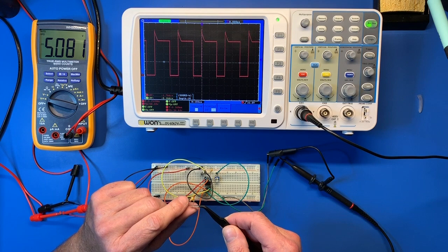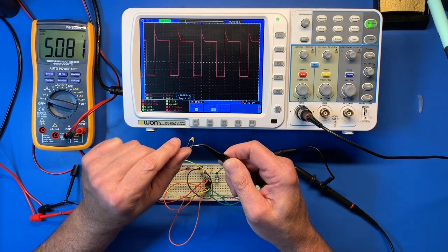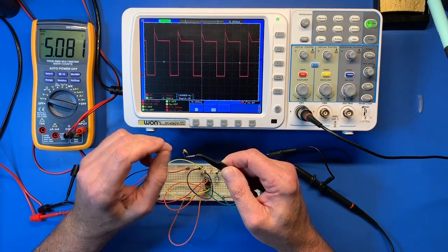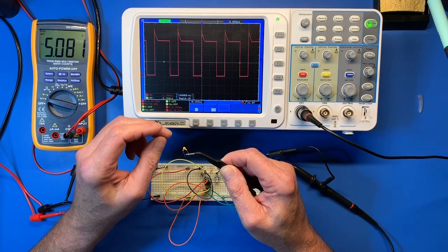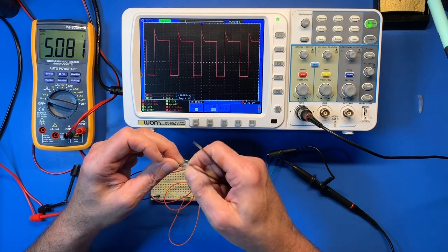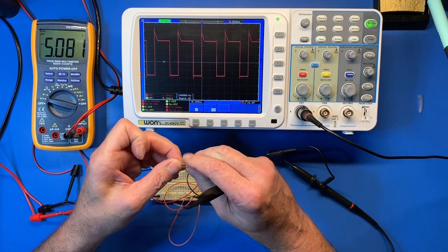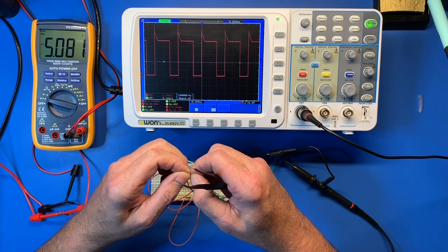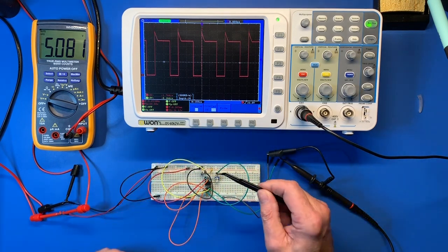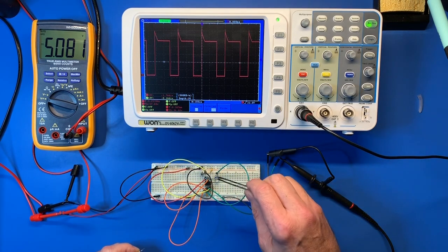This is a little 0.01 microfarad tantalum, and usually you use like a 0.01 or 0.1 microfarad for decoupling. It's a good range for the range of frequencies we're interested in decoupling off of the power supply line. So I have a little spot here. I can try to slip it in, but it's going to be kind of tricky.